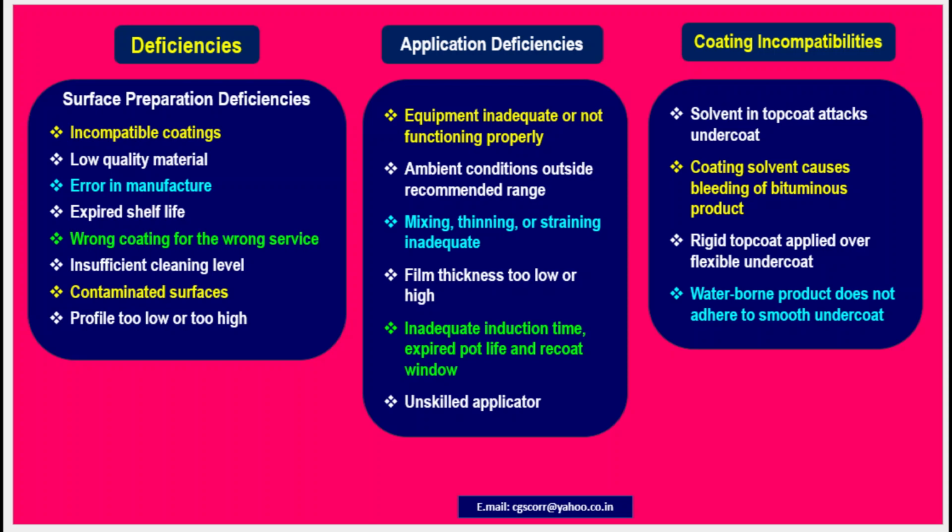Then application deficiencies. Under this, equipment inadequate or not functioning properly, ambient conditions outside recommended range, mixing, thinning or straining inadequate, film thickness too low or high, inadequate induction time, expired pot life and recoat window, unskilled applicator.